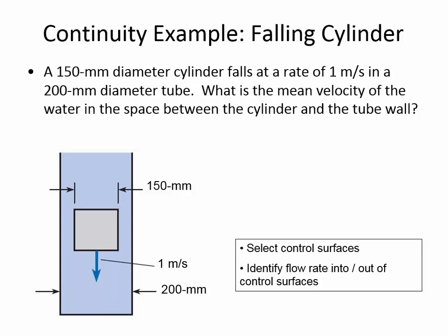Basically today's experiment is just a process of adjusting the flow rate after you've added a certain amount of mass to get it back in equilibrium. And you'll notice that there's 2 runs for each of the deflector plates, kind of like medium mass and high mass. And when it comes to the 180-degree deflector, it actually generates so much force that you'll be able to put most, if not all, of these weights on here, and that still won't be enough to get it back down into equilibrium. So you'll have to reduce the flow rate to bring the jet velocity back down.